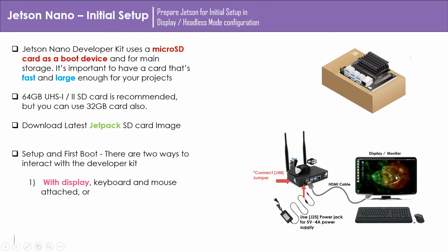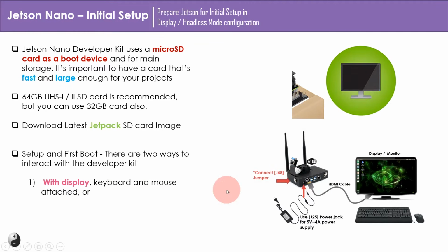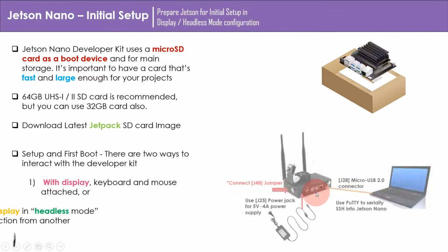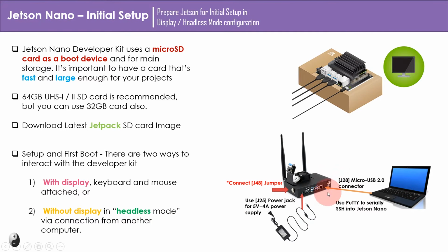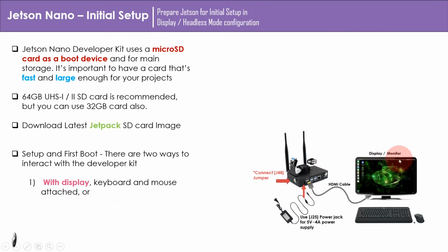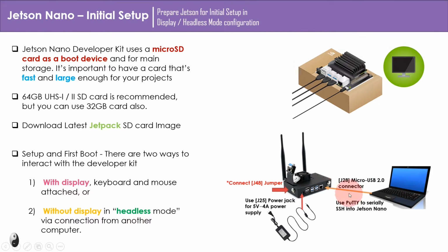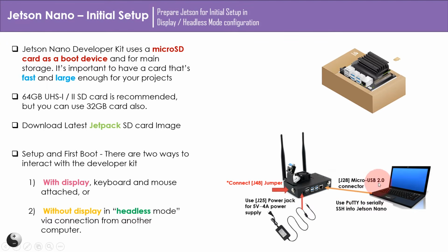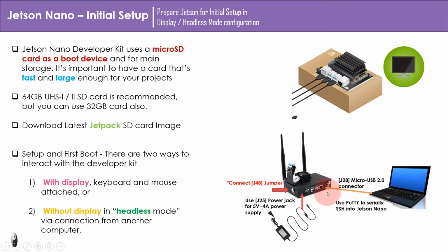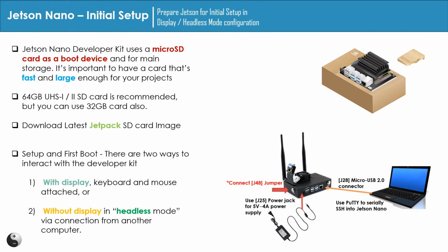In earlier versions of JetPack OS, there was only one way. A monitor display was mandatory. But after the release of JetPack version 4.2.1, the second method, meaning the headless method, was included in JetPack. So, even though you do not have a display monitor, you can do the initial setup through the serial terminal console by just connecting Jetson Nano to your laptop using a USB cable. Let's see the connection diagrams of both methods in detail.